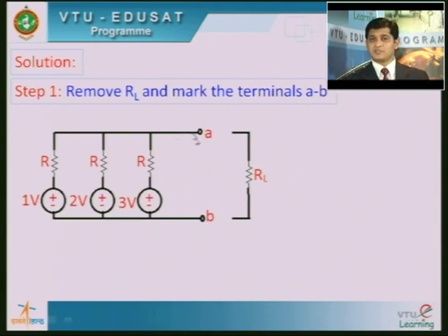So now what is possible to be done here? They are asking us to find the condition for maximum power transfer. Let's not bother about that. As of now, let's only think about what equivalent we can obtain across AB by Millman's theorem. So what can we do? We know we have 3 resistors and 3 voltages. Use the equation for E and Z to obtain 1 R and 1 voltage. So let's try to do that now.